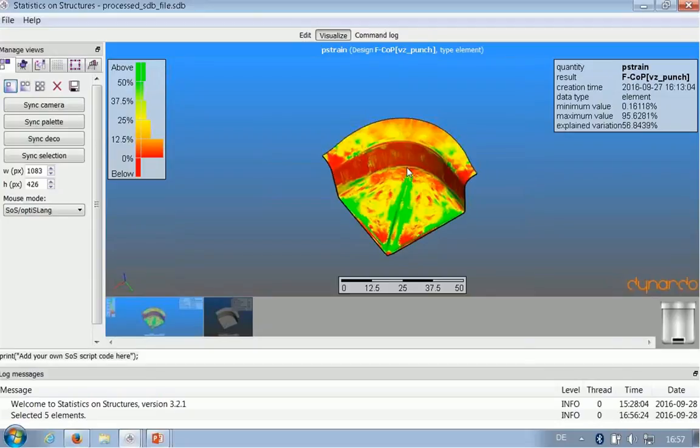As already promised to you several times, we can also detect hotspots in a simple and fast manner. Hotspots are nodes or elements of interest, typically measure regions with large scatter. Hotspots might be of interest in simple robustness analysis, like determining the exceedance probabilities, or in an optimization task, like the minimum and maximum values among all samples.